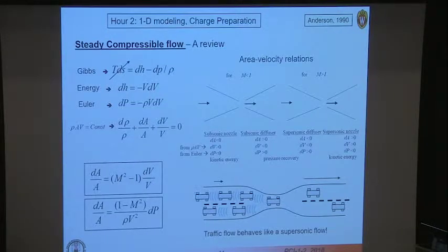If I look at an expanding duct or a nozzle, the area change is positive, the velocity change is positive, and the pressure change is negative. So I convert my internal energy into kinetic energy.